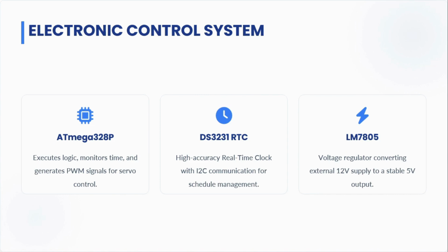To ensure our feeding schedule remains strictly accurate, we integrated a DS3231 RTC. This is a highly accurate real-time clock that manages our schedule. It communicates seamlessly with the microcontroller using the I2C protocol.